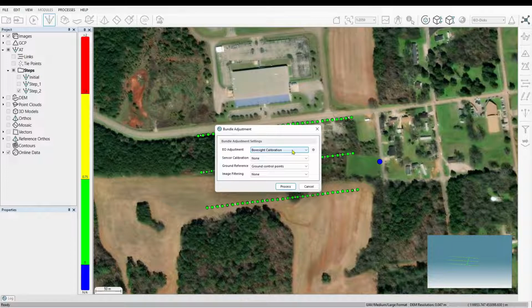And honestly, that's because when you're using a system with an IMU and airborne GPS, those values are typically known from the manufacturer or from when you put that piece of equipment in the aircraft. You would never need to run a bore site calibration in Correlated 3D because that's already been done. That's for somebody who's probably building their own system or trying to back calculate or figure out if anything has changed, so they could do that.